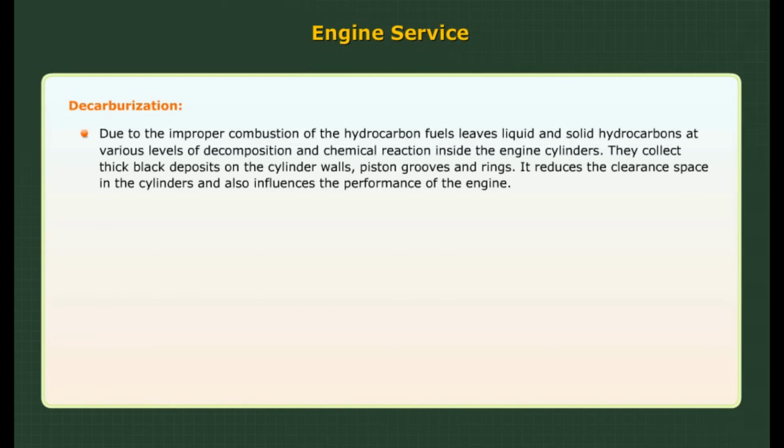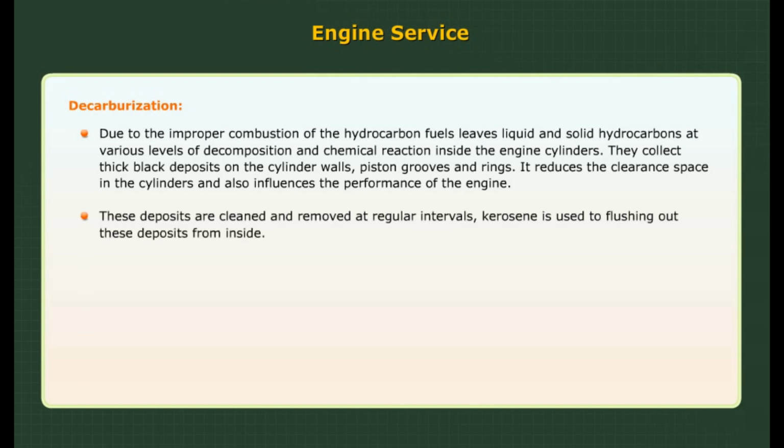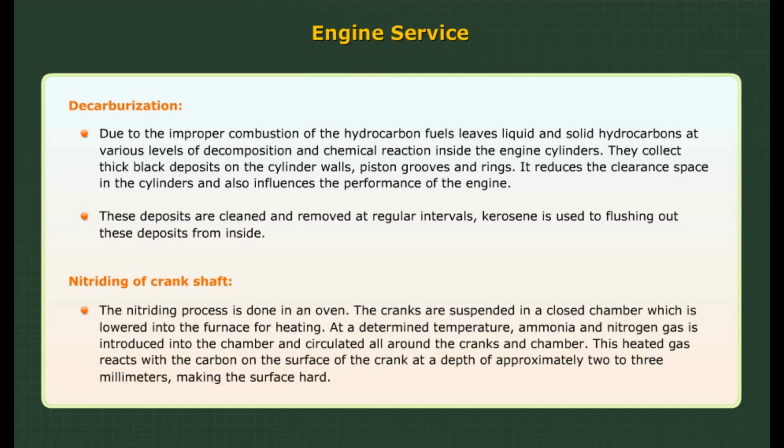Decarburization. Due to improper combustion of the hydrocarbon fuels, liquid and solid hydrocarbons are left at various levels of decomposition and chemical reaction inside the engine cylinders. They collect as thick black deposits on the cylinder walls, piston grooves, and rings. It reduces the clearance space in the cylinders and also influences the performance of the engine. These deposits are cleaned and removed at regular intervals. Kerosene is used to flush out these deposits from inside.